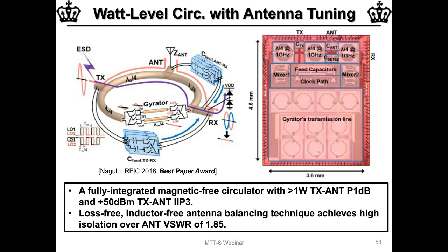I think there are some other open questions still. The phase noise question is something that I mentioned. I think we have a handle on it, but it's something that we have to demonstrate experimentally, that even in the presence of a powerful transmitter signal, the phase noise of the clock will not degrade performance. That's one open problem. The other open question, I think, is this: when you have perfect clocks that are exactly 0 and 90 degrees,